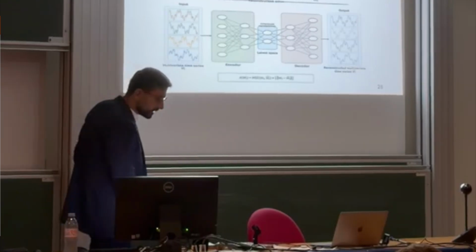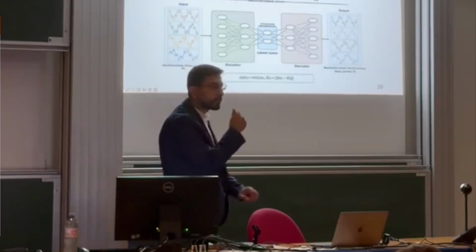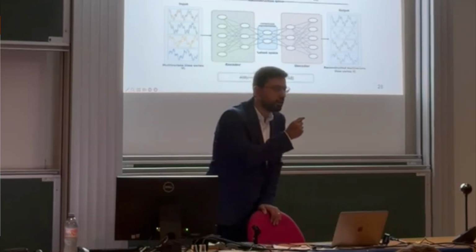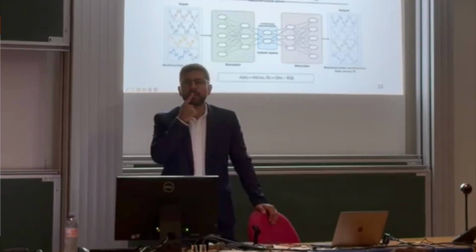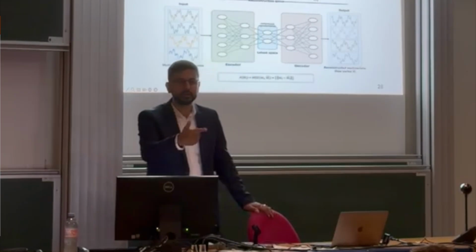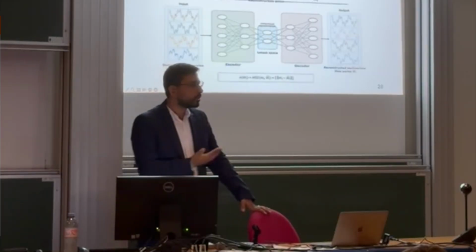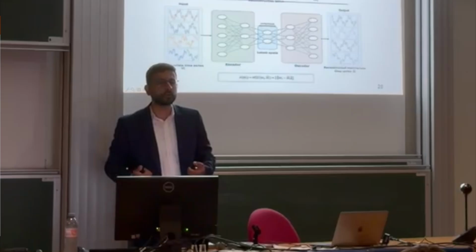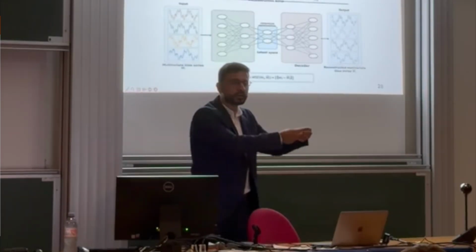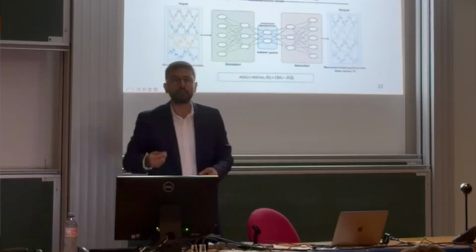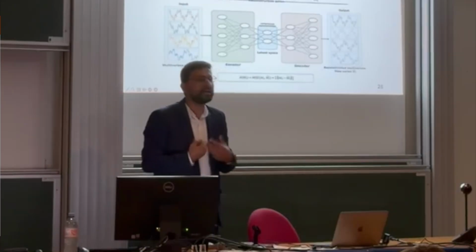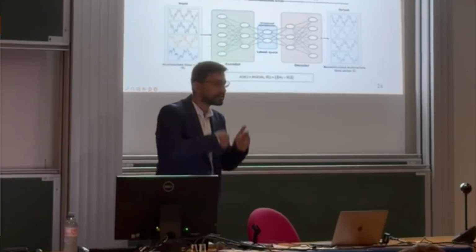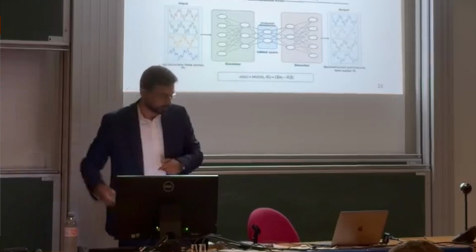This leads to the following: when we are training on the normal operation mode, we will have a low reconstruction error. Then when we face real, new online data, if we are receiving normal operation mode, we will have a low reconstruction error. While if we face an anomaly, something deviating from normal operation mode, we will have a higher reconstruction error, thus detecting a fault.